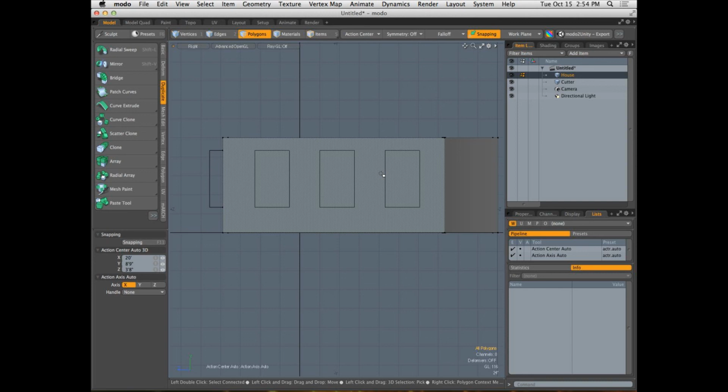With its default values enabled, the work plane doesn't seem like it has much of a role inside of our system. But in actuality, the work plane has a lot of consistent components that we're used to seeing in other locations. Specifically, the work plane has an origin. It has a center point. We can't see it initially, but it does. All planes have a center point. I want the center of my work plane, which is the only snapping guide inside of our system that can move, to be in the center of this polygon.